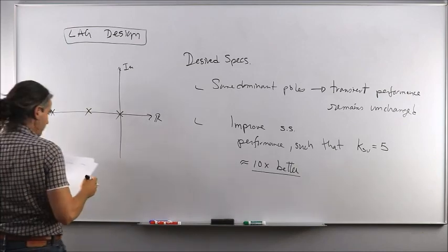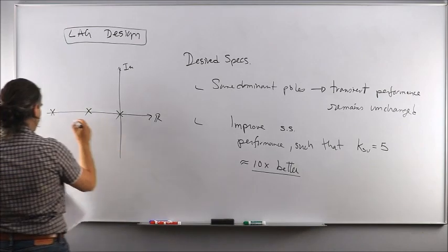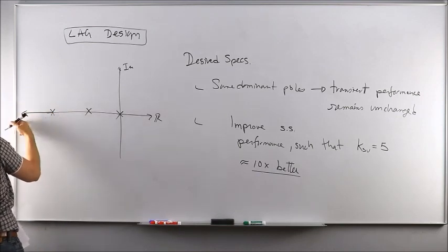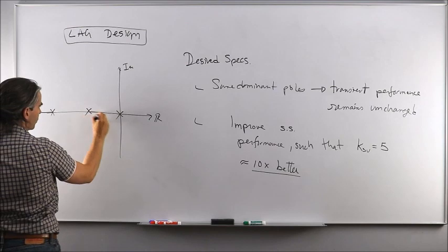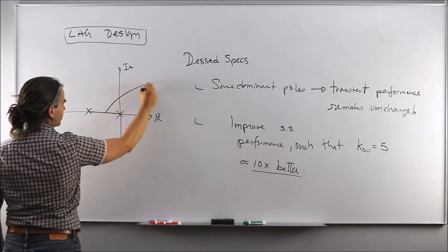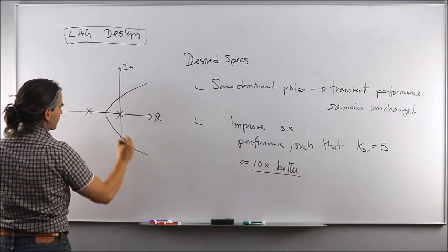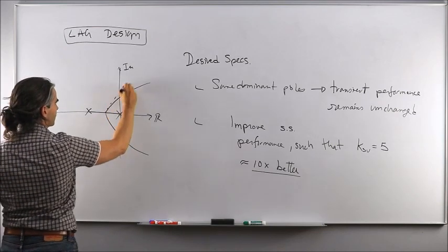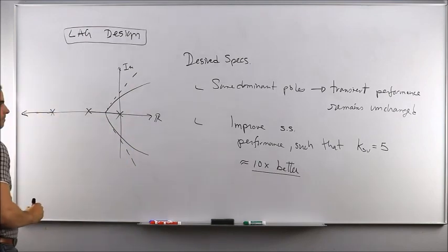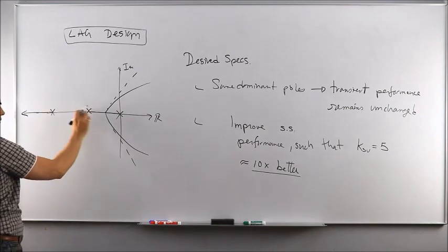Those are all the open loop poles. If you look at a closed loop root locus, one pole would fly off to the left. Those 2 poles would meet here and would fly off along asymptotes, right? Because we have one asymptote here and one throwing everything to the left here. And no root locus in between.